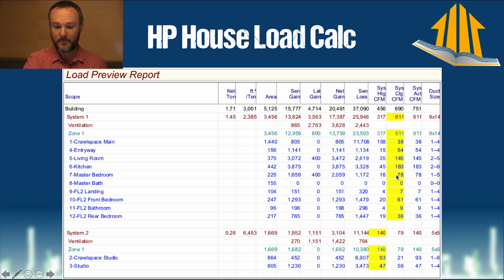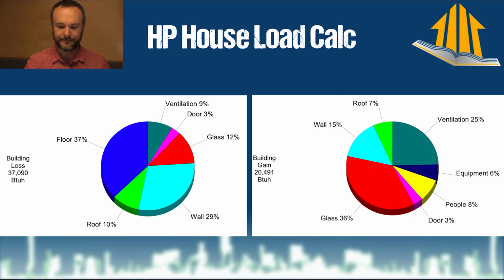And you can see the CFM over here. I've got a total of 600 CFM that I need to move, which is what a 1.5 tons of air conditioning moves. A ton moves about 400 CFM in order to get the relationship right where you're bleeding out the heat and the humidity. You can play with that with the speed taps, and an HVAC professional is the one who should be doing that.